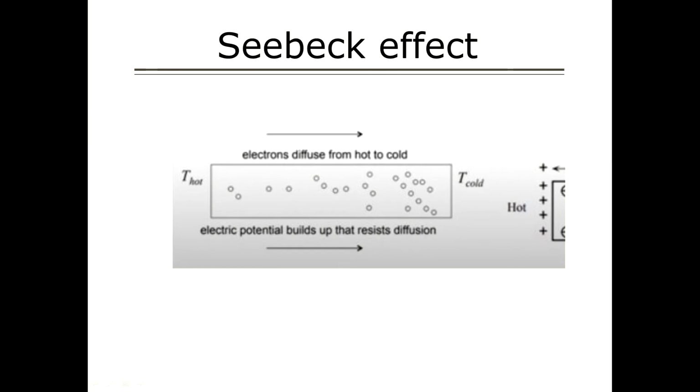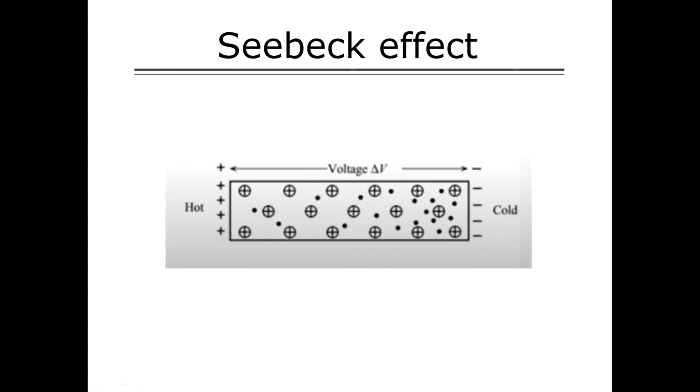On the hot end, the electrons get heated and gain energy, thus move to the cold end, and therefore a different temperature will be formed at the hot end and cold end. Then an electromotive force (EMF) is induced in this closed circuit. The amount of induced EMF differs for different metal combinations and is proportional to the temperature difference of the junction. This is the basic thermocouple working principle.